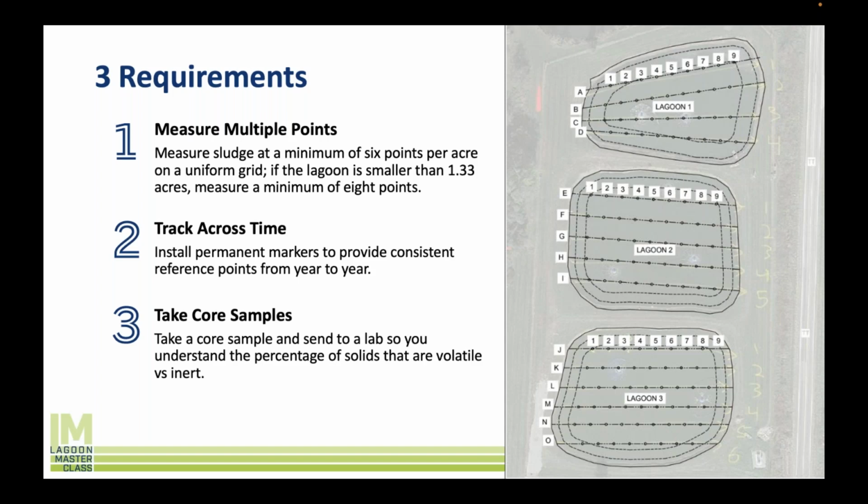So we're taking a lot of measurements here, and we're making sure that we're getting a really good sense of how much sludge is in this lagoon based on all these different sampling points. Sludge does not equally distribute itself across the lagoon, for your convenience. It really doesn't. It accumulates in certain spots and not in other spots, and it's kind of all over the map. Second thing, track across time.